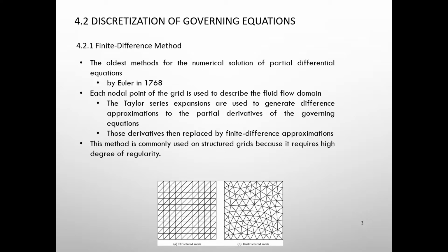Okay, the continuity equation is quite similar for any kind of problem because it just applies the conservation of mass. Meanwhile, for the momentum equations, it depends. If your problem is laminar, you can just use the normal Navier-Stokes equations. But if your problem is turbulent, you need to use the one that we discussed before.